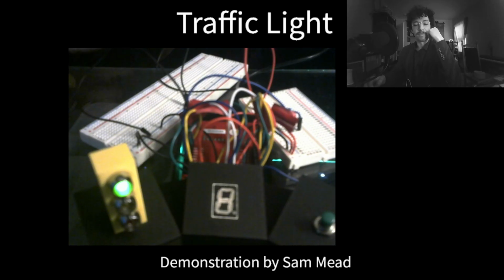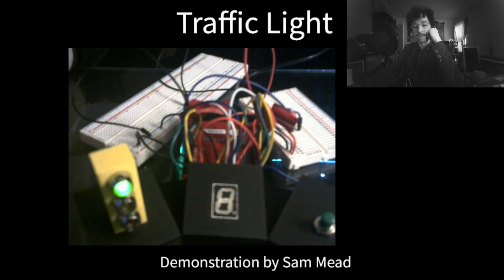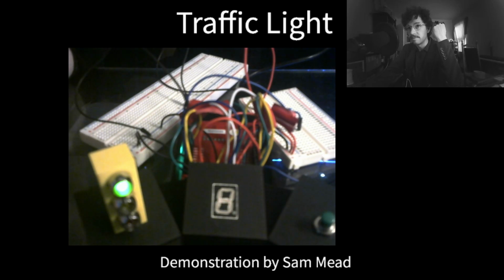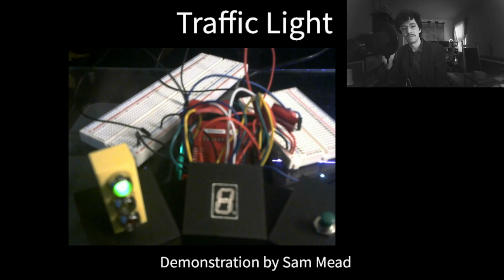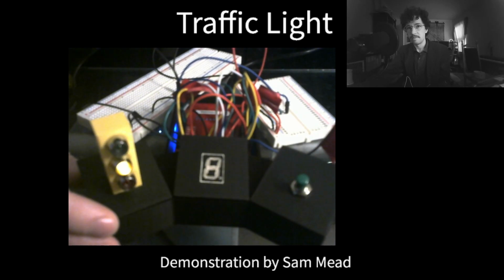And as I've said, we have the 7-segment display on port B, taking up most of the pins on port B, and the LEDs and the switch are both on port F, kind of taking advantage of the natural implementation of port F, where switches live on pins 0 and 4, and outputs on pins 1, 2, and 3. So that is about it for the ports.